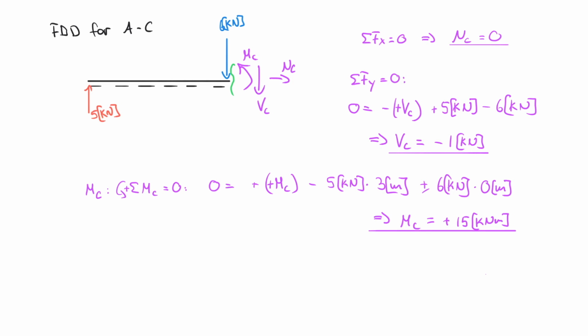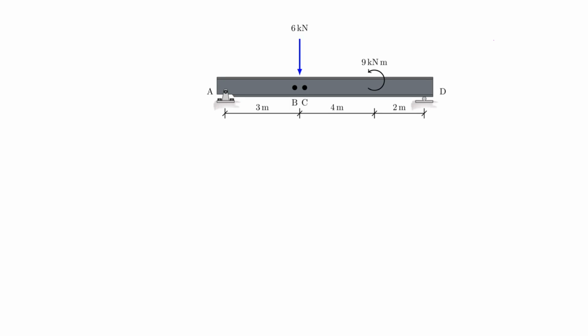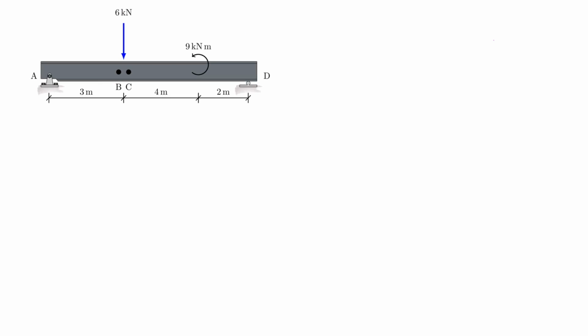but for educational purpose I want to move on from here to the concentrated moment that would be acting somewhere here, and I'm going to pull in the reference here real quick to help you understand what I'm talking about. So let's actually bring in this picture and let's now find the internal forces to the right of this moment. You can yourself determine them to the left of this moment, but for speed reasons here, I'm just going to look at that location. And to do that, I'm drawing my free body diagram of that portion. And also this will give us an opportunity to use the left cut actually. So now I'm cutting right here.